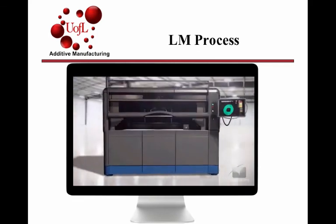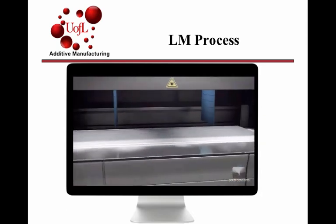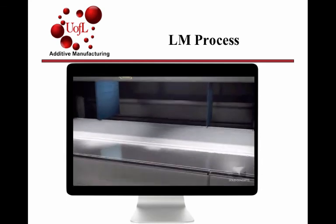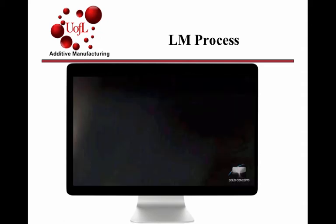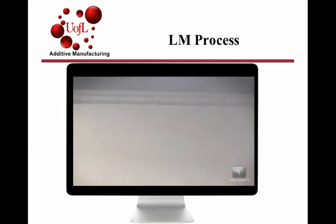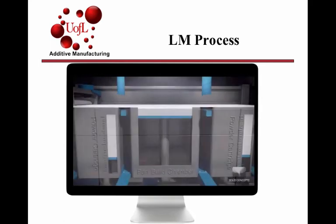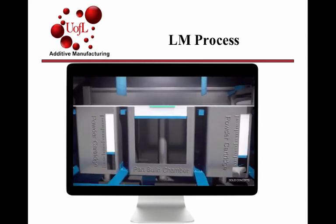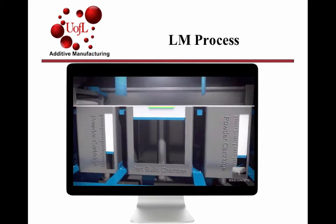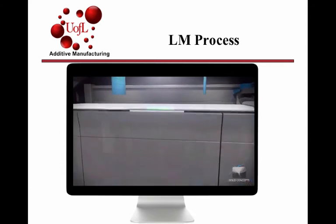The machine then begins to create the first layer. After a leveling roller spreads a thin layer of powdered material across the powder bed, a CO2 laser traces the cross-section on the material. As the laser scans the surface, material is heated and fused together. Once a single layer is complete, the powder bed is lowered to make room for the next layer. More material is introduced from the powder cartridge and rolled out smooth, while unused material is recycled. The process is repeated, building layer upon layer until the part is complete.